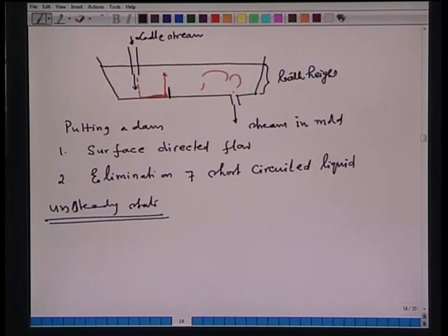One is the initial period, where you can either remove the cast product of the initial and then accept the rest. But towards the later stages, when the ladle has emptied, you have to bring the next ladle in between that time. The continuous casting process does not stop.